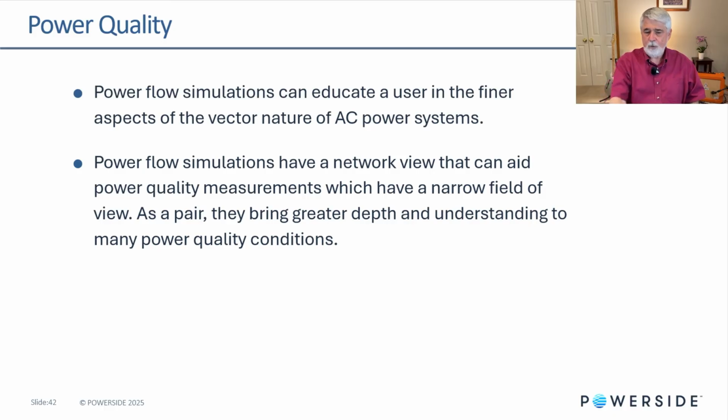The second to the last one, power flow simulations can educate a user. This is important, and a lot of people may not realize you can do this with a power flow, but I use it for this purpose all the time. Power flow simulations can educate a user in the finer aspects of the vector nature of AC power systems. If you don't quite get why voltage is dipping or not dipping, run some power flow cases. Look at the conditions. Try to understand what's happening here, okay? Use the power flow to help educate yourself.